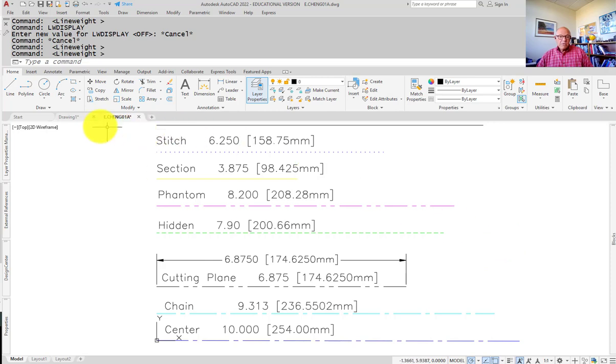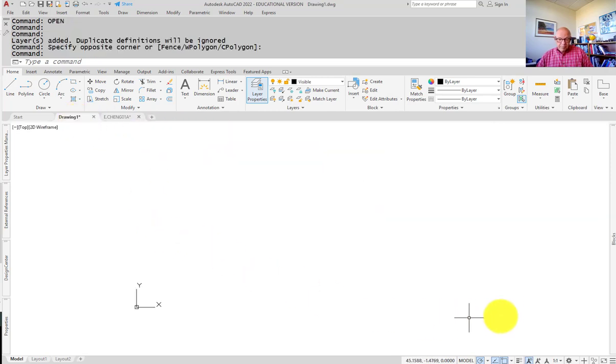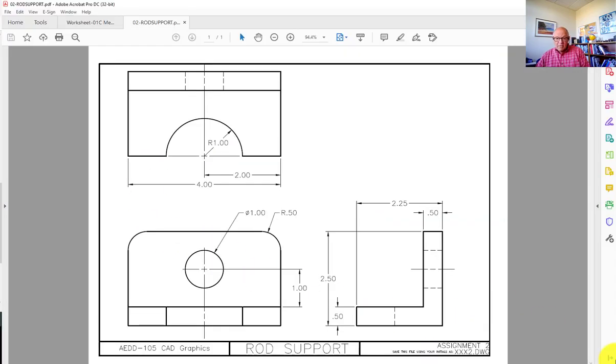So I'm going to go back to this drawing. Now, here's the drawing that you're duplicating, and this drawing is simply a very basic orthographic drawing, and you're going to follow the rules for orthographic projection that you learned or are going to learn in print reading, where you have a front view looking directly at one surface of a part. In this particular case, we're looking at what I'm going to call the front, and you draw it 90 degrees from your eye so that it's just the outline.